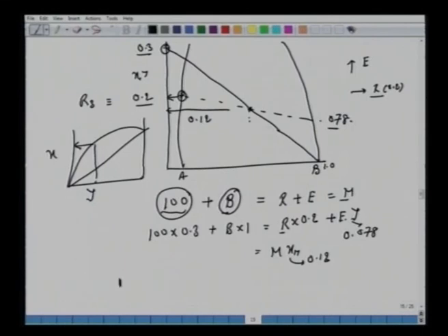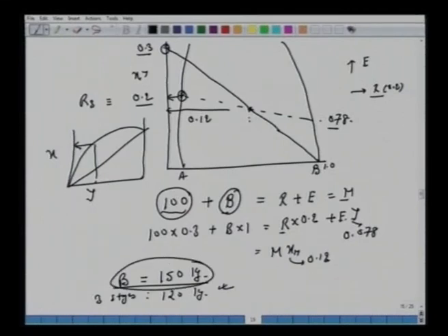All right. So this example we have chosen for this lecture is cross current 3 stages, where we added a fresh amount of solvent at every stage, and we were asked to identify different compositions. We drew the equilibrium curve. Graphically, we said that we can solve graphically as well as mathematically. But we have to plot both the y versus x diagram, equilibrium, and draw the rectangular coordinates, fraction of the solvent, and y versus x.